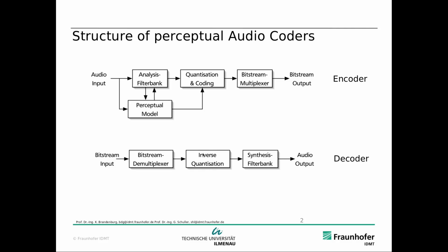It's not exactly inverse because we cannot really invert quantization. So I rather say dequantization instead of inverse quantization. So here this basically gives us the quantized values of those spectral components back, the subbands, spectral subbands. And then the synthesis filter bank basically makes a full spectrum audio signal out of it. So basically this recreates the original audio signal.